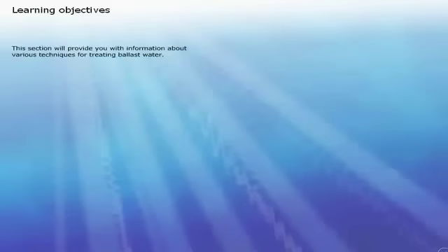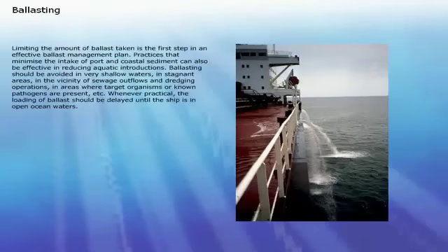This section will provide you with information about various techniques for treating ballast water. Limiting the amount of ballast taken is the first step in an effective ballast management plan. Practices that minimize the intake of port and coastal sediment can also be effective in reducing aquatic introductions.